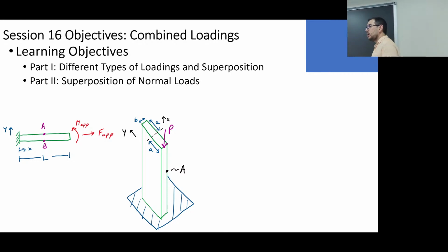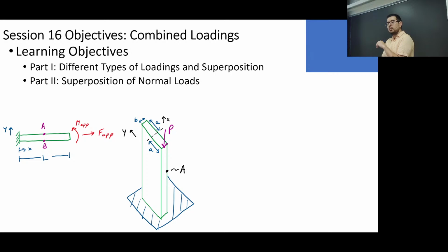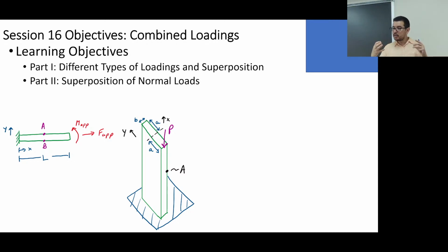You could imagine, I don't think I have this example in this particular session, a pressure vessel that's got pressure on the inside, and somehow I've got clamps that I attach to either side. I don't know why I would do this, and I start pulling it apart. Okay, so now if it's positive pressure on the inside, I've got an axial stress, PR over 2T axially, and I'm pulling it apart, and that's going to be F over A, where A is the area of the annular cross section. Of course, where there's air on the inside, it's not handling that stress. So you could imagine adding the PR over 2T plus the axial stress that I'm pulling with, okay?